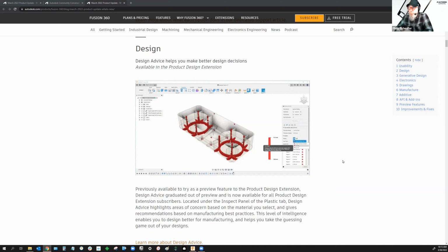So bringing that rules-based design pattern to plastics I think is just incredible, because instead of picking a sheet metal gauge, you say, I'm using ABS plastic and I have a rule that says all of my ABS parts are 2.5 millimeters thick, or whatever it is, let's say. They have certain bend radiuses, the kind of things you would associate with sheet metal design. All the little things you have to specify are now there for plastics.